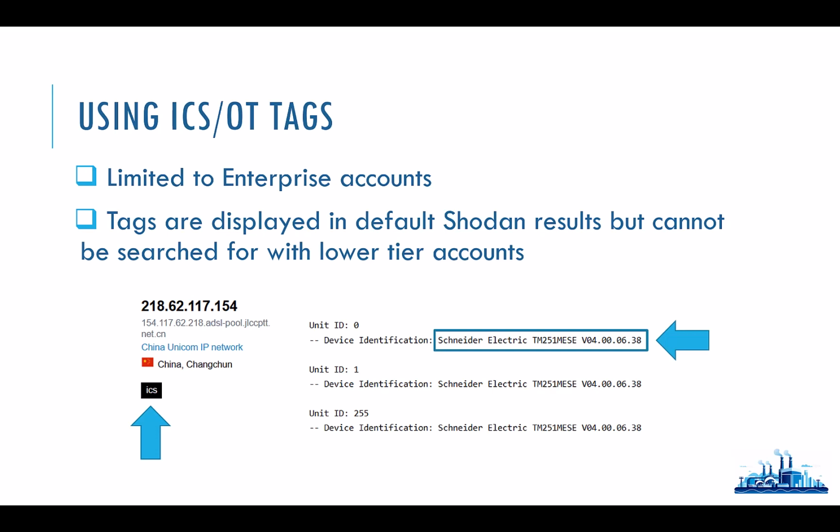Shodan found the device running on TCP 502, found the service exposed, and ran some additional communication to see if it could get the device to respond and determine, hey, is this really a PLC running Modbus or not? In this case, it looks like it really is.